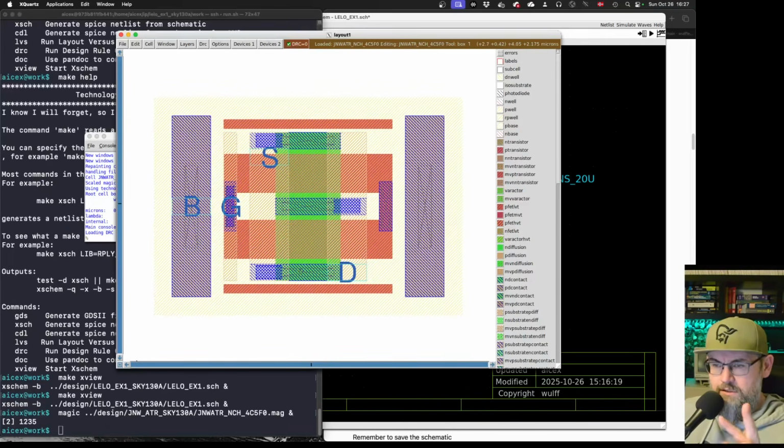I like these type of transistors because even if I flip them vertically, then I have currents going in both directions, because it turns out that the direction of current in silicon actually changes the effective mass of electrons, and that can have an impact on the current in a transistor. So if you want something that's actually properly matched, you can either select to have all the currents in the same direction in the silicon, or you can do as I do here, just flip them, because then you have both, and it doesn't matter what you do with the transistor, and you don't have to be that careful, so it's nice.